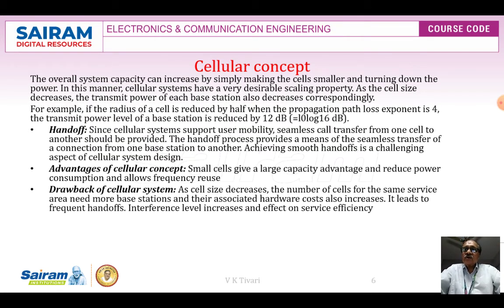Cellular concept. The overall system capacity can increase by simply making the cells smaller and turning down the power. In this manner, cellular systems have a very desirable scaling property. As the cell size decreases, the transmit power of each bit also decreases correspondingly.